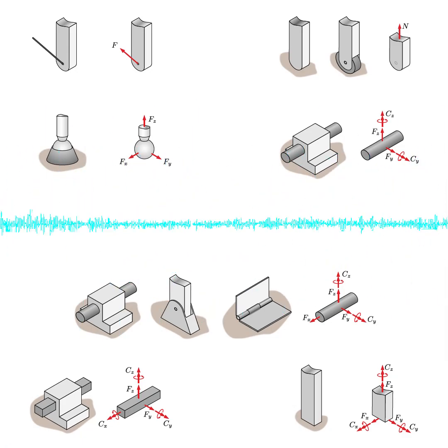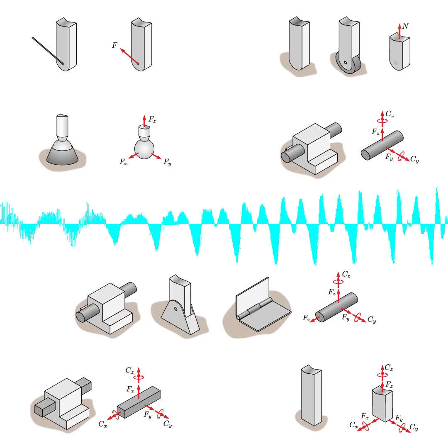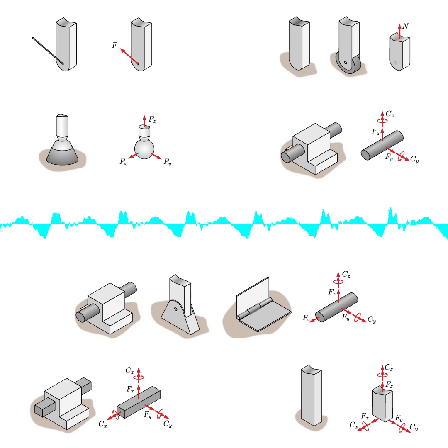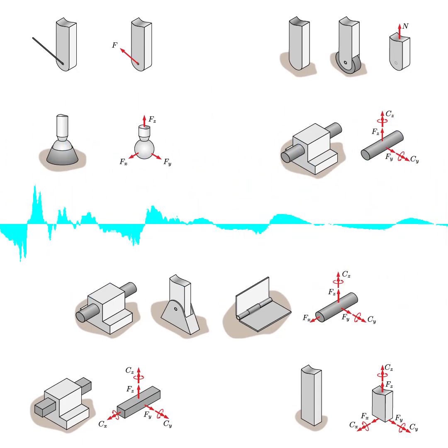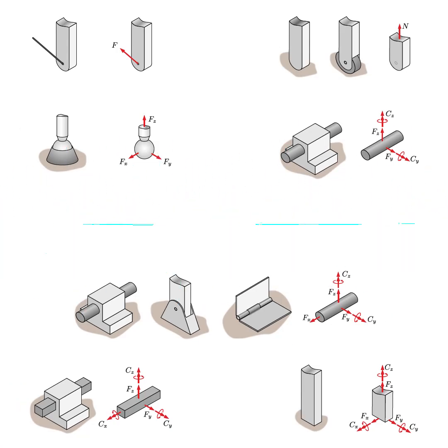So while that set of equations is a common starting point, it's not the only option. You could, for instance, replace one of the force equations with another moment equation. So maybe take the sum of moments about a different point B. As long as the three equations you choose are what's called linearly independent, meaning one isn't just a combination of the other two, then they'll give you the same information. That's handy. Does the source give us any tips on how to choose these equations wisely so that it makes solving the problems easier? Yeah, it does.